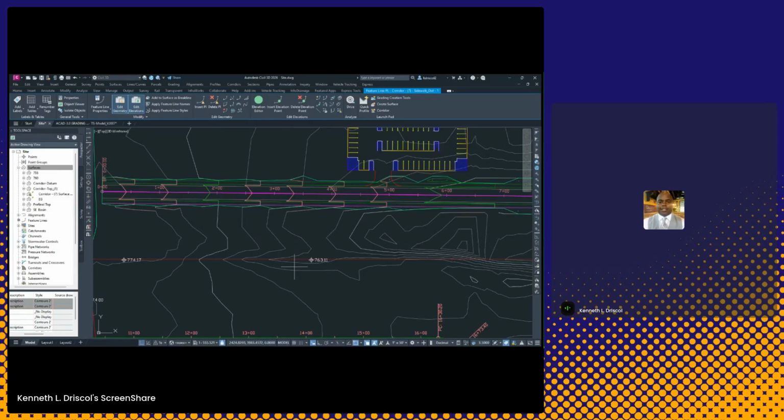and I said, okay, I want to go a distance of 30 feet. And I pick this point, then it says at the command line, specify elevation difference, grade, slope. I want to go grade of 5%. Then it creates that. I hit enter. Then I'll pick this feature line one more time.